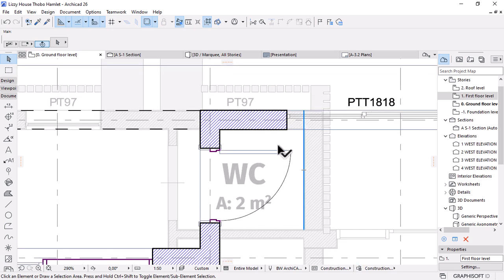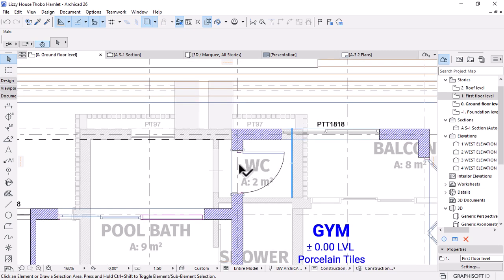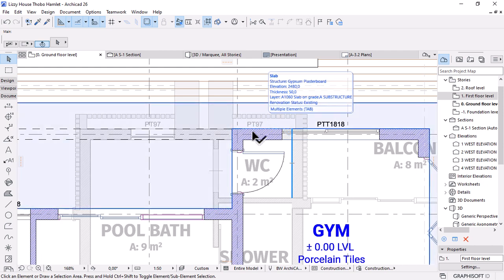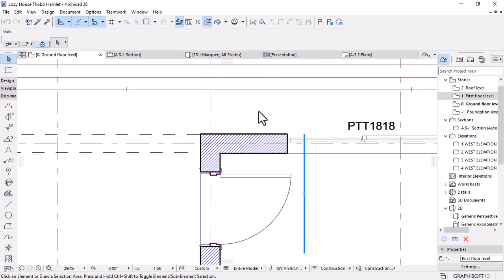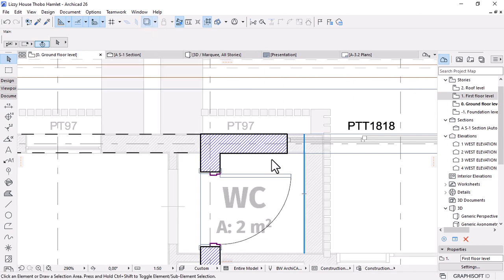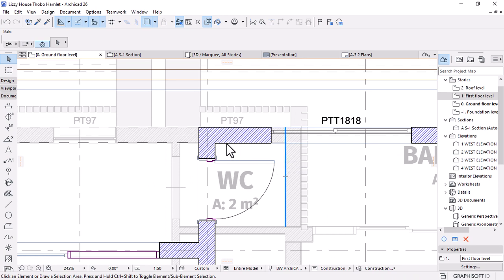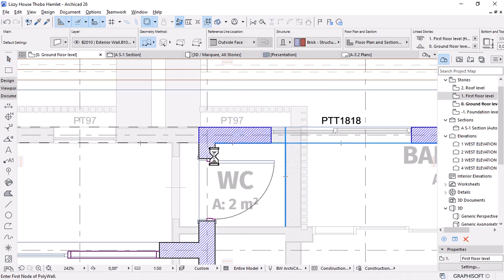So we have a toilet here that will need a duct. From the top we've provided these shading louvers to hide the pipes and the window for this. So we need to provide a provision of collecting the pipe from the top going down here. So what I'll do, before we switch off the trace reference, I'll pick the parameters of that and provide a duct here.